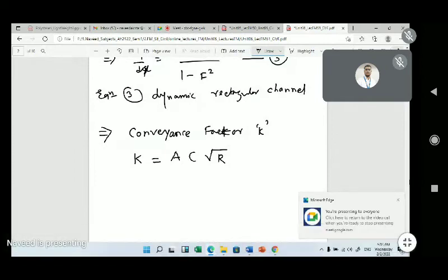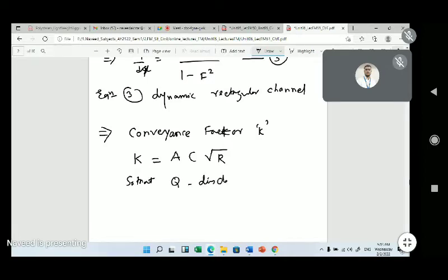So you can write down that Q, the discharge, is constant, and the formula for Q is equal to A into V, and it can be written as C A under root of R into S. C is the Chezy constant, A is the cross section.